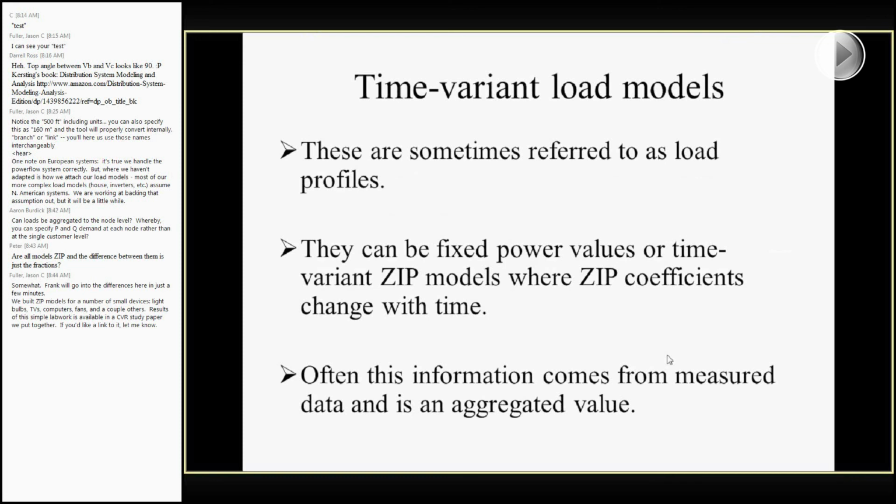If you wanted to play in a data file of measured SCADA data or something similar to that, you could apply that to just an object load and play that value in as a constant power, but it's a time-varying power, and that'll give you an accurate representation of what your load was doing without going down into all the depth of the 2,000 houses that are attached below it. So that might actually be a better answer to the question that was posed earlier.